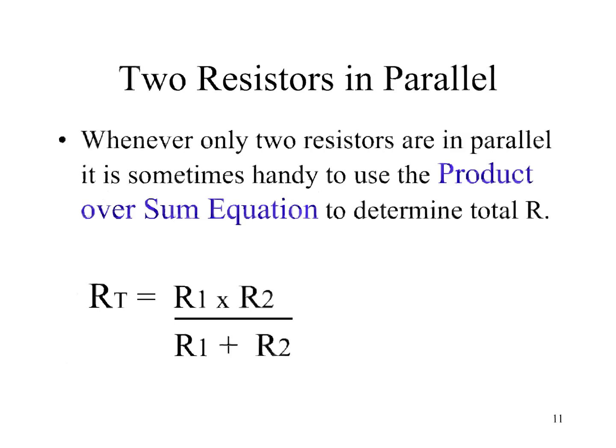So it's used often to do a prediction of parallel resistance, even just in your head, without having to find a calculator or whatever. And it's simply this: R total equals R1 times R2, the product, over the sum, so it's adding R1 to R2.